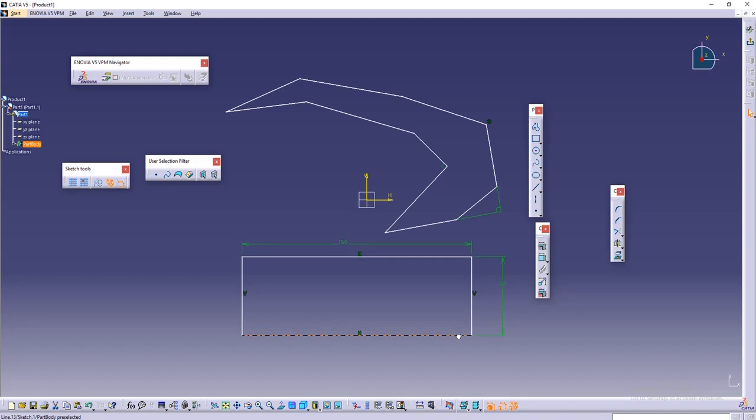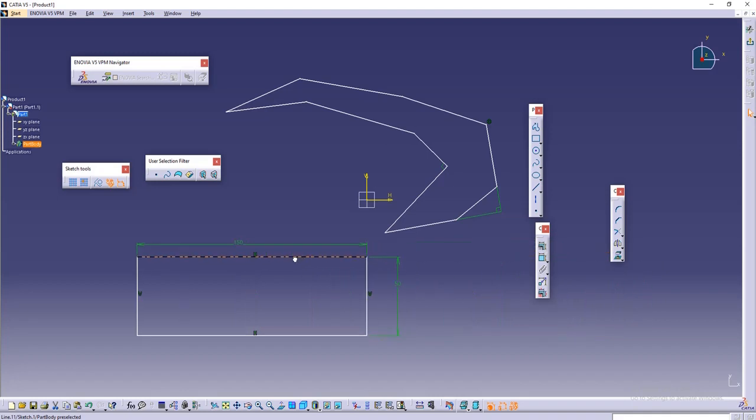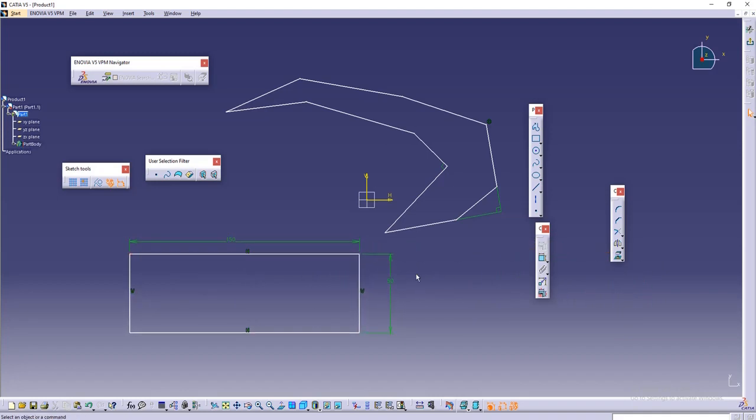So another important thing in CATIA is that whenever you are creating something, it has to be with reference to your origin axis, right? So this is outside the axis, right? So whenever you are creating any sketch, you need to give some dimensions for where the sketch is generated and how far it is from the original context, right?